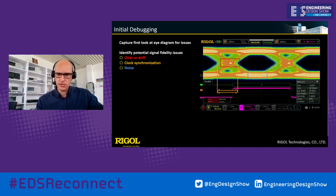You can see this with the 0 or with the 1, and the thickness of the 0 and the 1. You can also see how closed your eye is on the vertical side because of the noise. And the jitter and the drift close your eye on the horizontal side. This can be measured as well with the eye diagram. Furthermore, the rise time, which you can see in the green box here, has a direct relation to the bandwidth which is used for this data transmission.